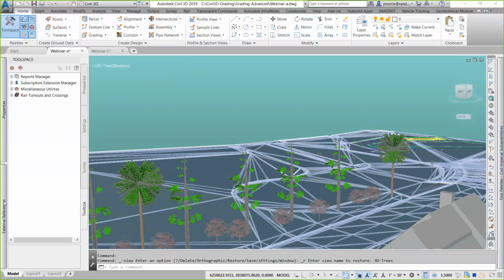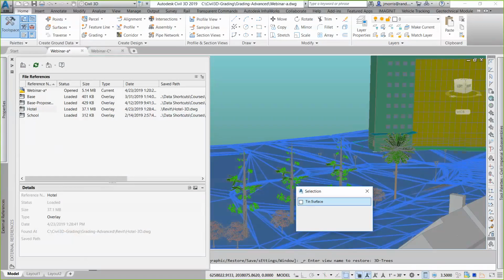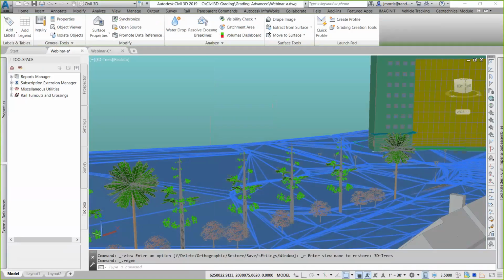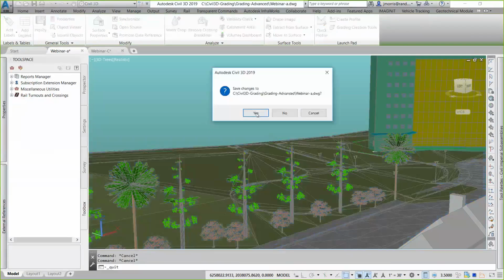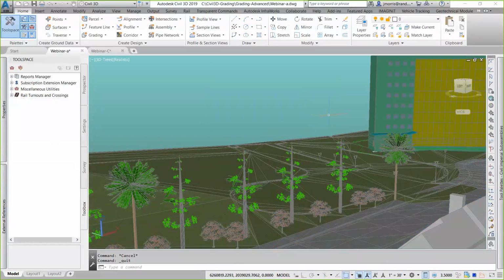so if I go to my XREF manager, all I need to do is to swap my 2D out to 3D. So simply 2D to 3D, hit Enter. So it kind of behaves as a multi-view block. There it is. It's really bogging down. But that's why I like to rename my XREFs, simply swapping out 2D and 3D. I'm going to close out of this. It's bogging down a bit too much.